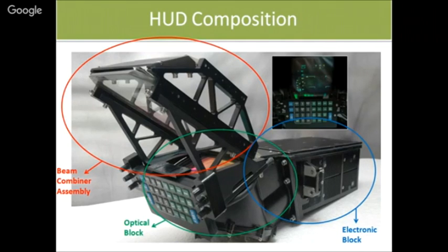So since this optics collimates it, it is projected onto infinity and only one wavelength is reflected back. And the selection of that color is also very important, because yellowish green color is NVG compatible. With night vision goggles, the pilot is able to see this yellowish green color. So that is the reason that particular color is used. Now they are specifically coated to reflect, and then it is projected onto the eyes of the pilot.